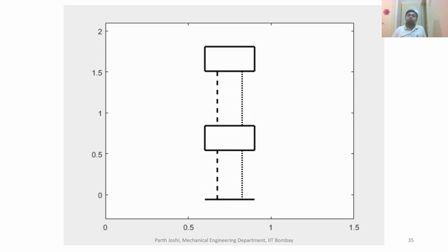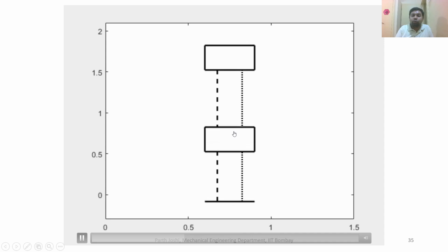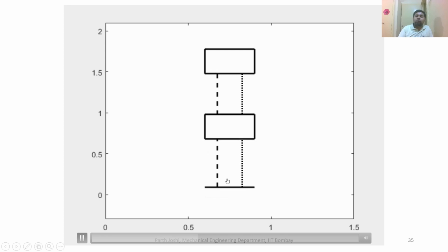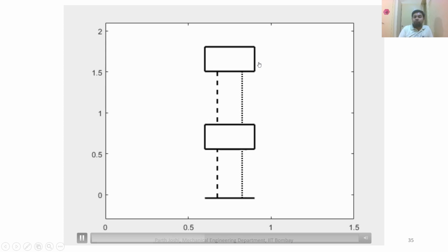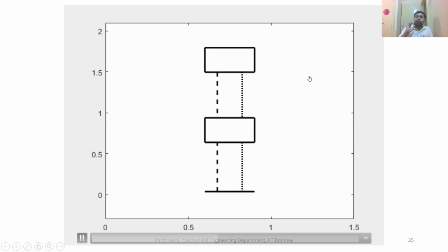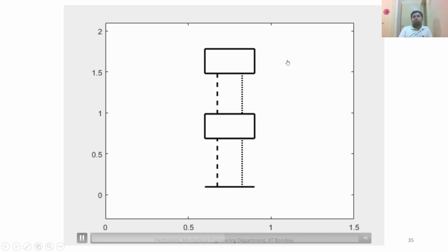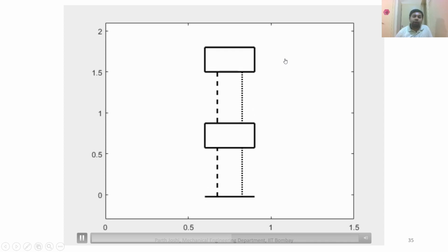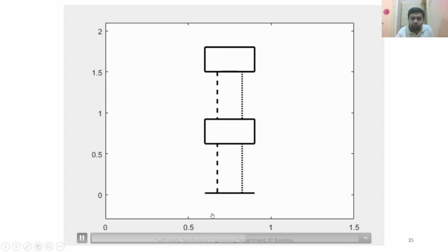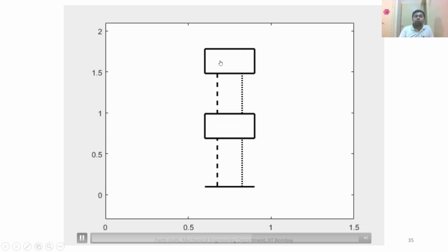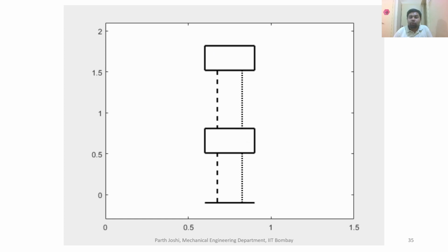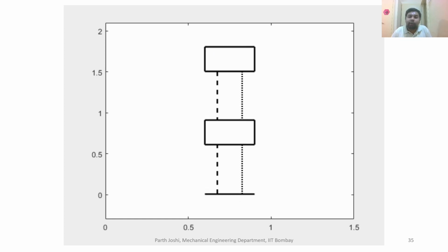If you observe carefully, you would have noticed that the lower mass, which represents the wheels, is moving much more up and down as compared to the upper mass, which is representing the car body. So we are able to successfully achieve our design objective, which is having the movement of the car body as little as possible as compared to the bump. The amplitude of the road bumps is much more than the extent by which the upper mass is moving up and down. This is an animation that you can create in MATLAB.